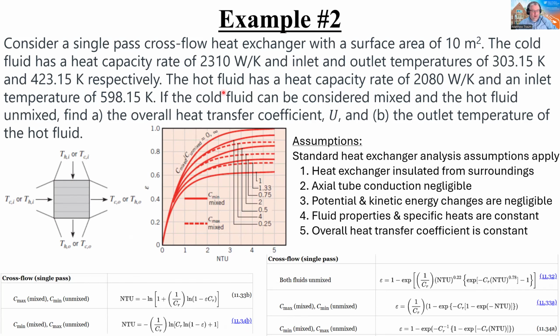I don't care if you're an American units person, please convert it to Kelvin, do all your math in Kelvin so there's no problem with division or multiplication. No issues with non-absolute temperatures. And then when you get to the end, convert it back to whatever units you want. But all your heat transfer calculations should always be done in Kelvin so you never run into problems.